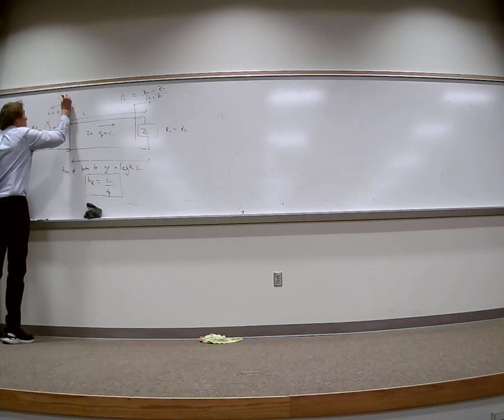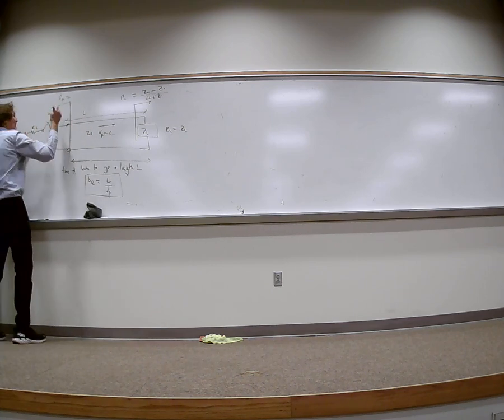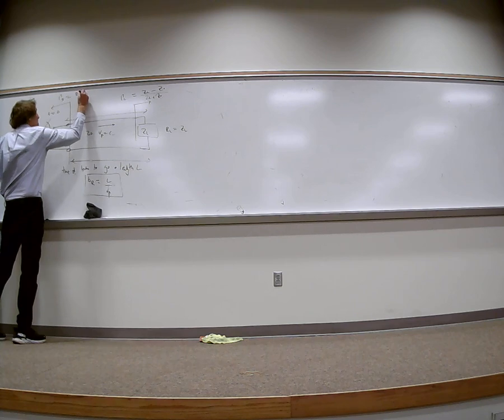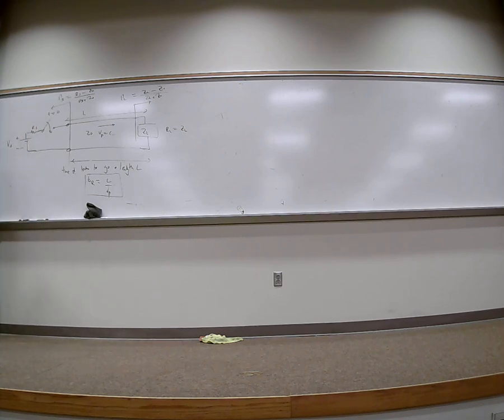And that's at the source. And that's going to be the impedance you're going into. Remember, it's coming from there going this way. So it's going to be RS minus Z naught over RS plus Z naught. Y'all with me so far?